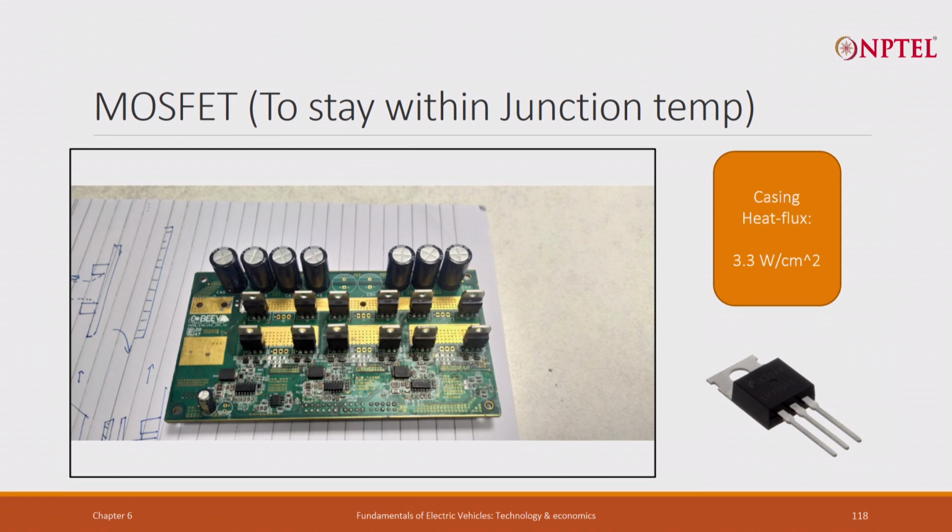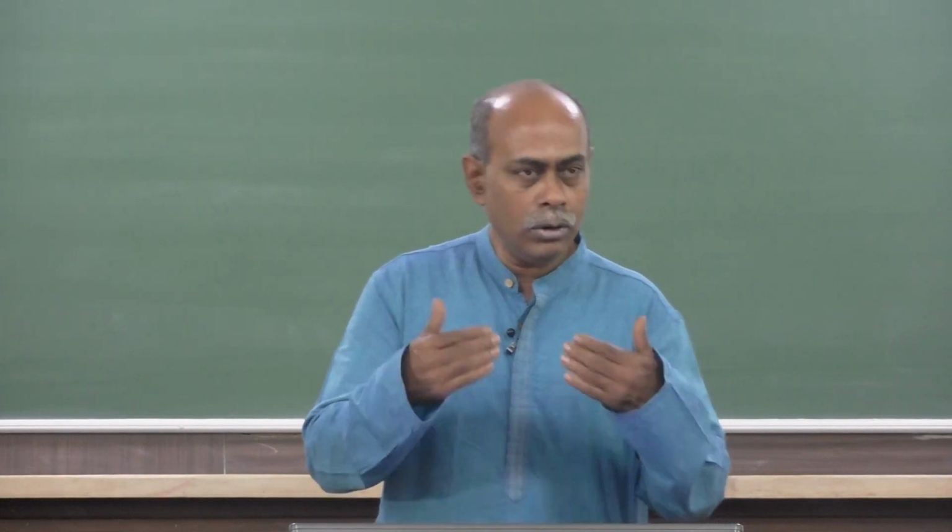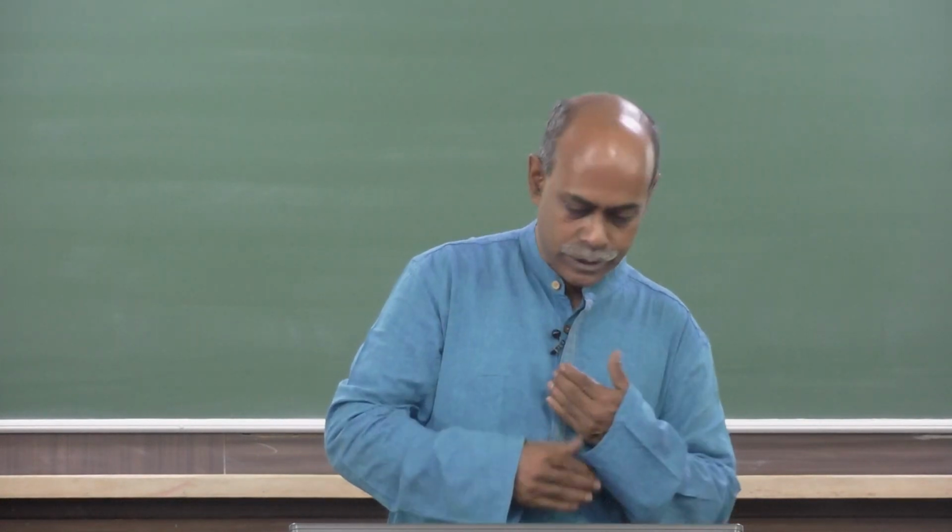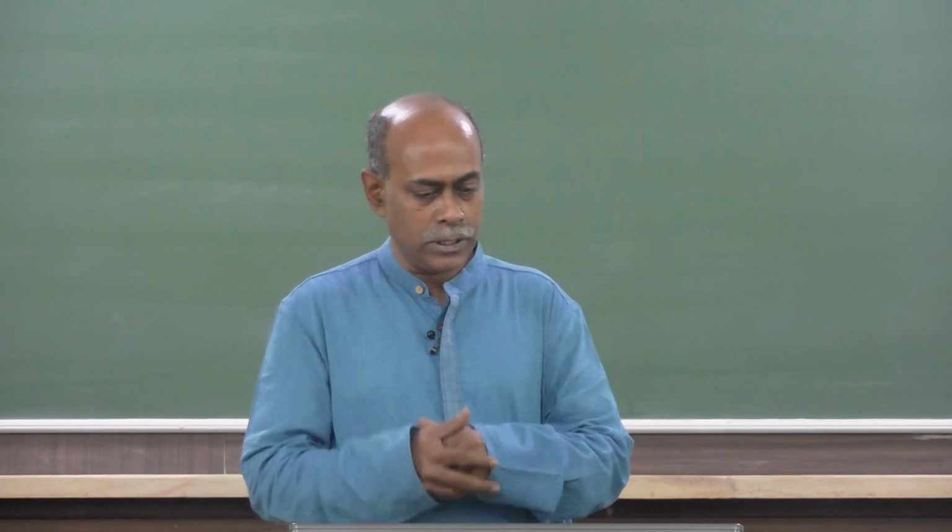But as we already discussed, the temperature rise depends not only on the heat generated, it depends upon what else? It depends upon the heat removal rate. If the removal rate is as fast as the generation rate, there is no further increase in temperature. So, how do you increase the heat removal rate is what we will be seeing in this little video.